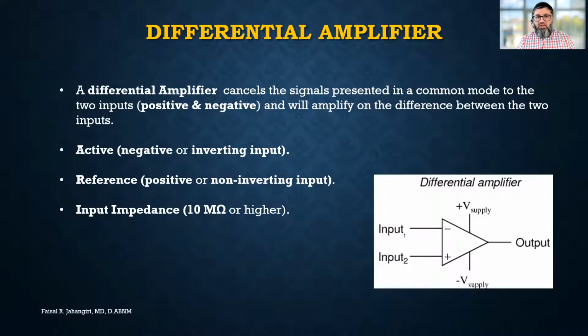So the same signal, if we put the input into the positive input, the second one, it will not invert and it will stay downward. So if your N20 is going down on the screen, that means it is being recorded either from the precentral gyrus or the phase reversal, or you have plugged into the positive input. The second input, the reference input, is known as the positive or non-inverting input because it does not invert.